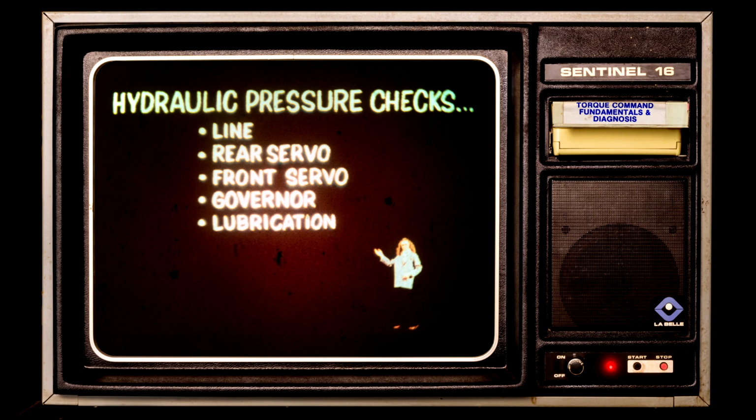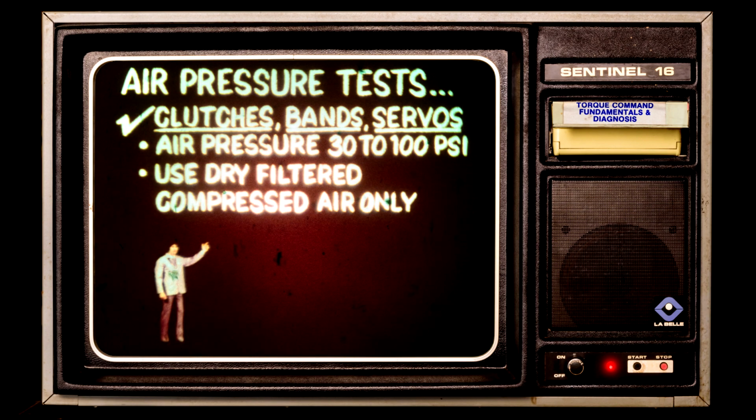Knowing about hydraulic pressure tests is important to you, but there is a third test method you can use. It's air pressure testing, which is next in line for explanation. Air pressure testing is used to confirm proper operation or leakage of clutches, bands, and servos. In these tests, air pressure of 30 to 100 psi substitutes for fluid pressure. Only dry, filtered, compressed air may be used.